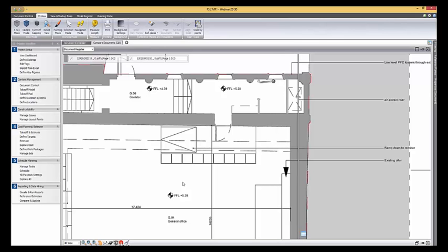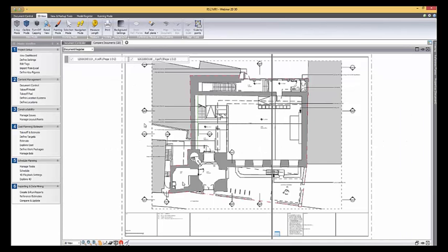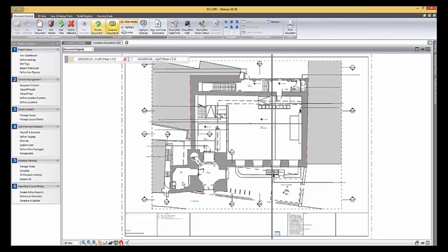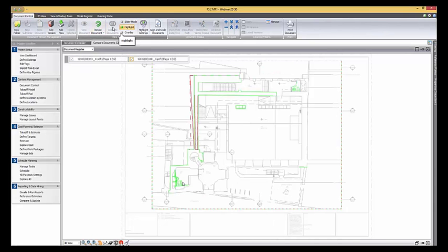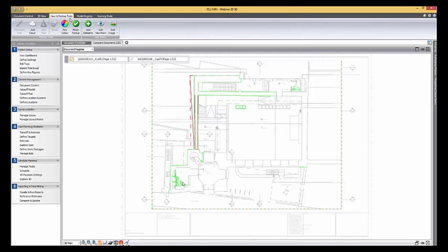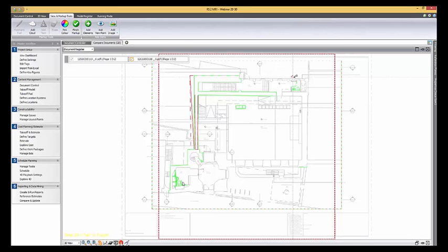So that's one tool. The other tool we can use is the highlight tool, which is basically redlining a drawing for you. This is all automatic, so it's just taken those two drawings and it's noticed that red are things that have been removed and green are things that have been added to the drawing. And then I can come in here and just add a little cloud, make a note, do some annotations.